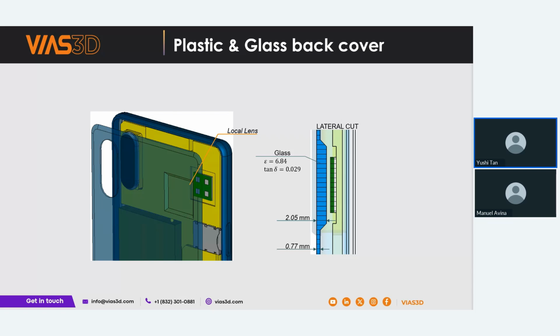However, the standard thickness of, let's say, 0.77 millimeter for tough glass suitable for handheld devices is quite far from the optimum thickness of, let's say, 2.05 millimeters in this case. So we already know that the standard thickness will have marginal performance. And in order to achieve good performance while not increasing the outside dimension of the initial design, we can employ certain techniques when it comes to localizing the area to be thickened.